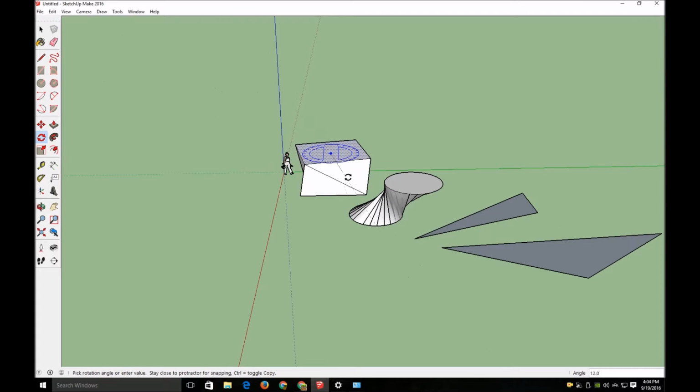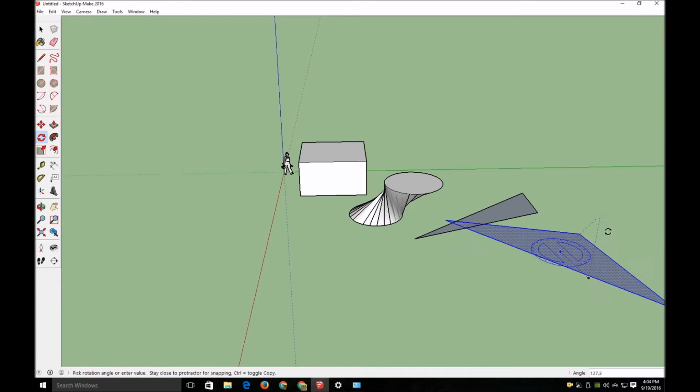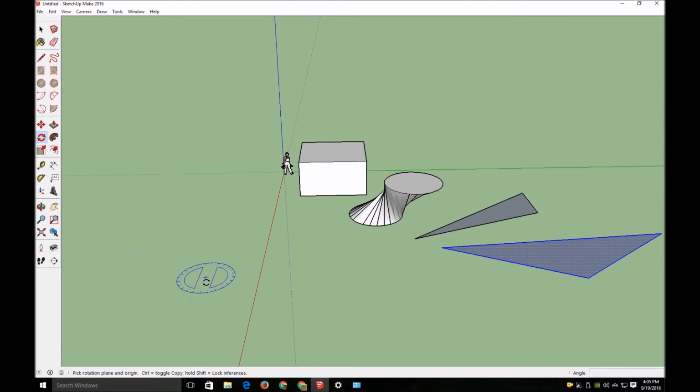Yeah, so if you, say, decided to want to rotate this, just select that, and then select the rotate tool, which is not the R shortcut. The shortcut R will bring you to rectangle. Select the axis, click, and it will let you regularly rotate it. I will undo that with Control Z, and then next is the move tool.